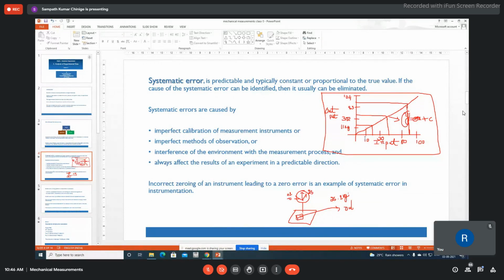So that means now from the system you know what your y is, right? You will get y. From that you will find out x. Now x equals (y minus c) by m, correct? (y minus c) by m is what your x is. So if you get 11 kg from the system and put 11 kg here, you already have the slope of the curve and you know the intercept, and therefore your x will be exactly 10.